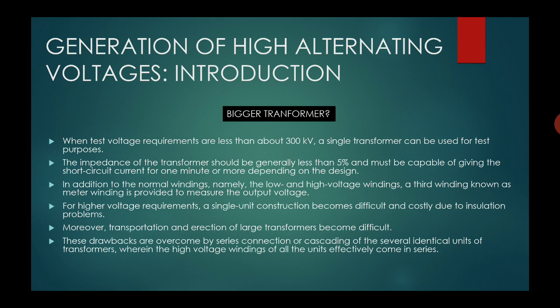The gist of these statements is that testing for voltages lesser than 300 kV can be done by a single transformer. But if you require a bigger transformer, there are issues of insulation, and you need more windings.